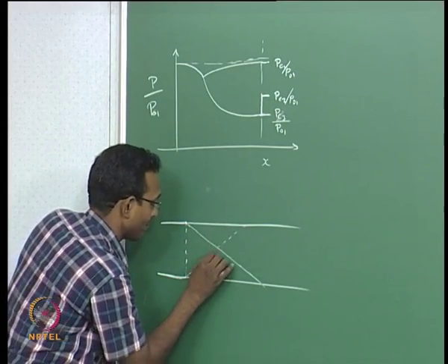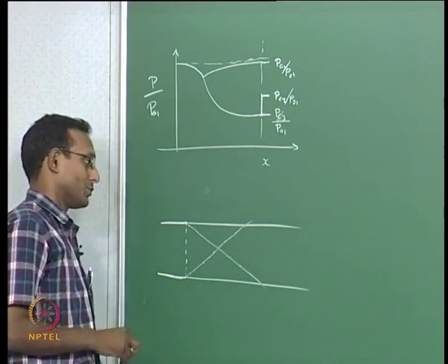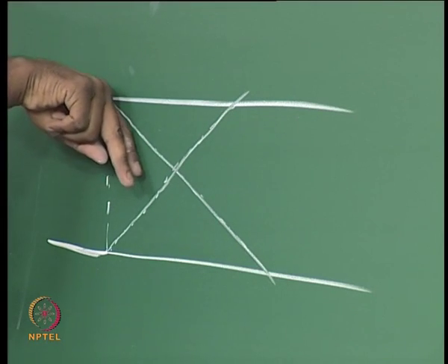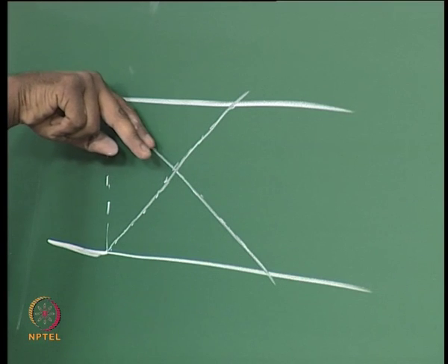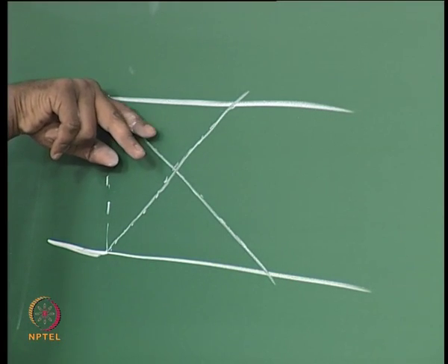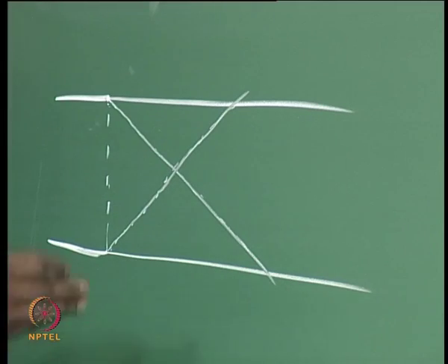So your expansion oblique shock that was inside just came out slowly and then became your Mach wave. After that, if I keep decreasing my back pressure, it is going to continue from there and send out expansion waves that way.